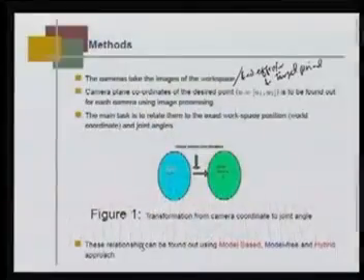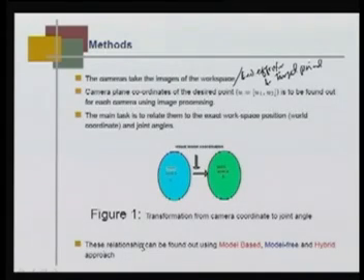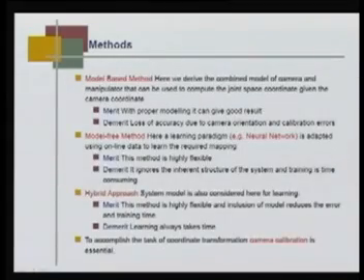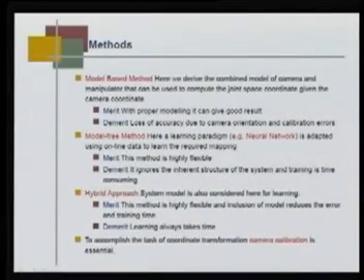Okay. So, this is the back calculation. What is normally done, calibration of camera means we take known x, y, z points and from there we see what the camera output is. We correlate them in terms of certain parameters, identify those parameters, and then inverse computing gives us from camera plane to XYZ plane. So, this is called the model based method. With proper modeling it can give good results, but there is loss of accuracy due to camera orientation and calibration errors. So, calibration has to be done perfectly.